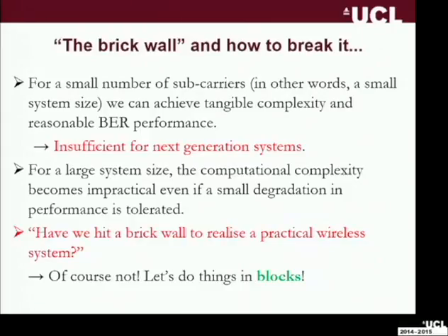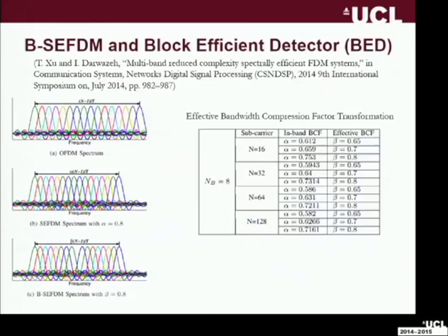And what we thought is, at the moment we've considered everything adjacent, all the carriers together, not really playing around with them. What if we start considering them in blocks, creating bands of subcarriers? Can we improve upon the performance? So we thought, well, yes, we can. If, say, every 8 subcarriers we null a subcarrier and then continue, you've got bands now of 8 subcarriers.